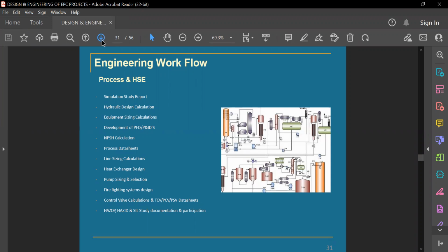Mainly these engineers will sit together, and the design team will have to say to the chairman that okay, my P&ID and my design is safe, and in any condition this will have a protection. For example, he will ask what happens if pressure goes high in this pipeline, then we will say that okay, a pressure gauge is there, a pressure transmitter is there, which will be giving indication in the control room via SCADA.